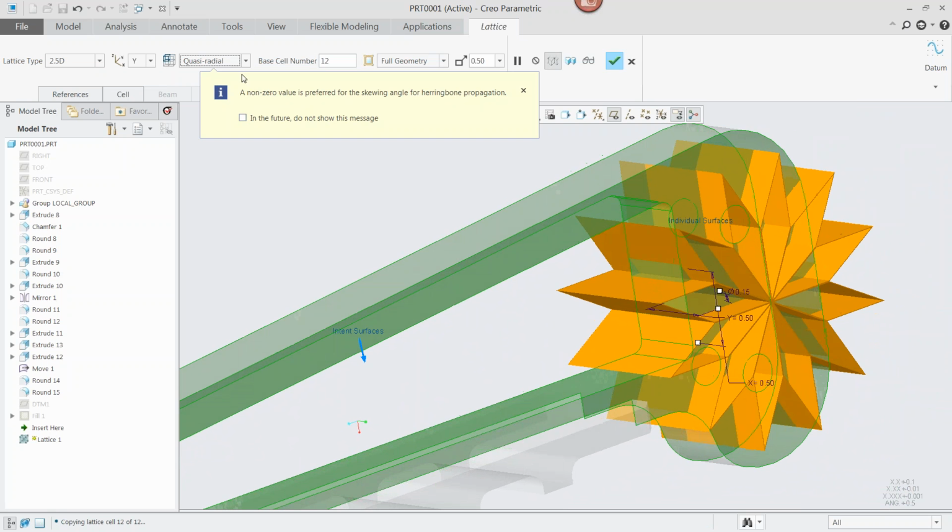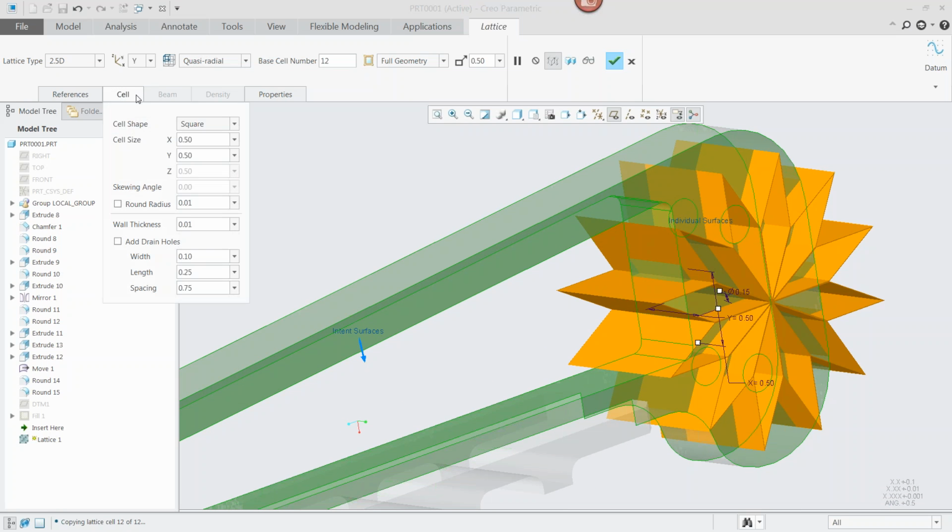And another cool feature is the ability to go into the shell. When you do 3D printing, you're going to have support material, and to get that support material out, you traditionally throw it into a bath. Now, if this was an external part, let's say the lattice was on the outside and visible, this isn't really a problem. But let's say you had the lattice on the inside of your part. You need a way to drain out that support material.